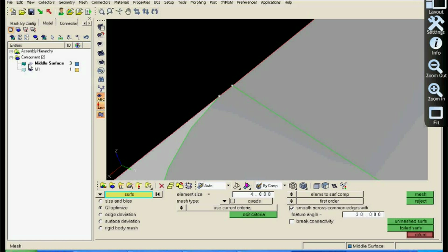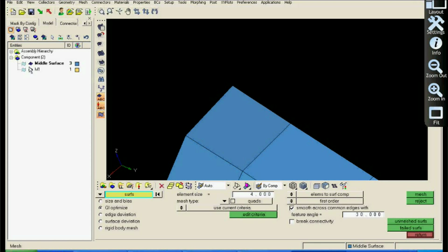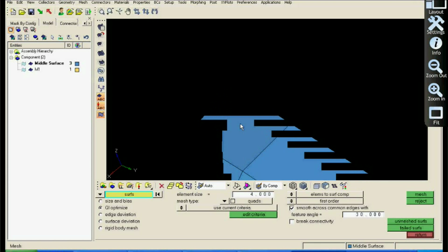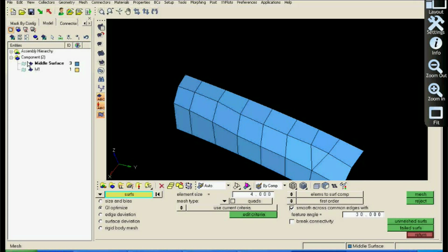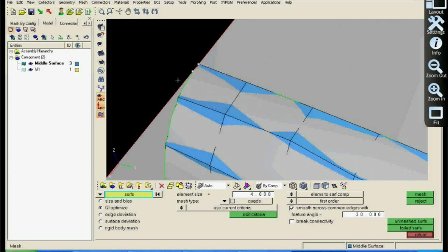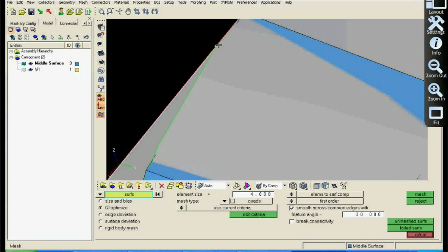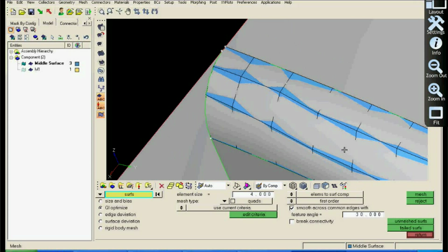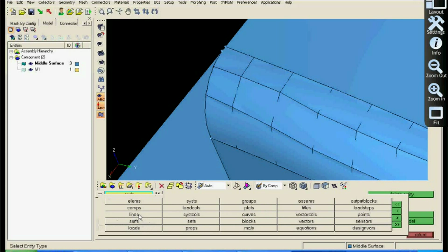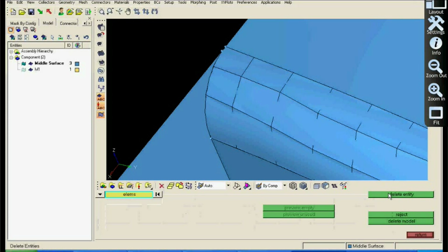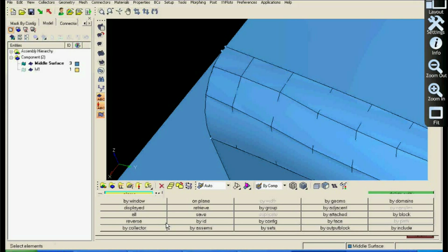You can see that because of these two nodes, it will try to mesh those parts, and it will try to keep both of them in the picture. So this is not that good, and what we can do is think of deleting that one node such that we have only one line. So let's try to do what we can there.